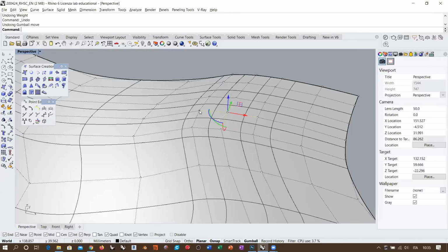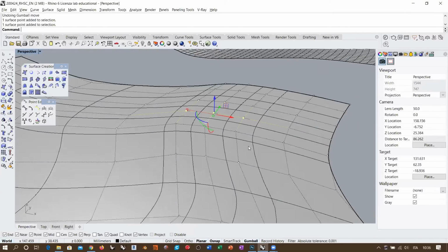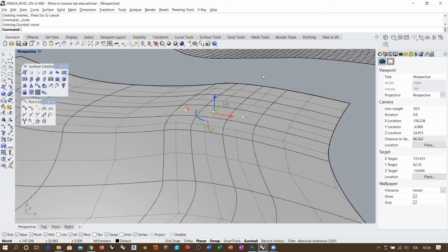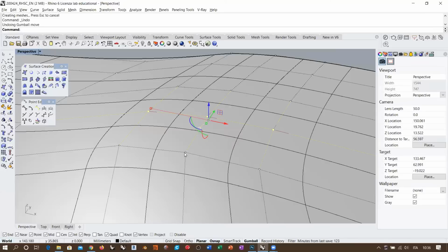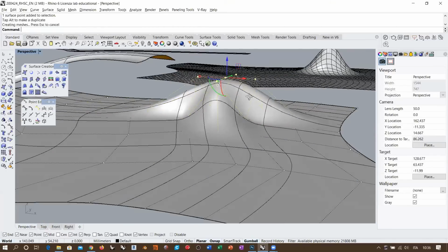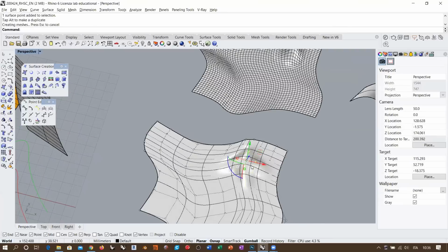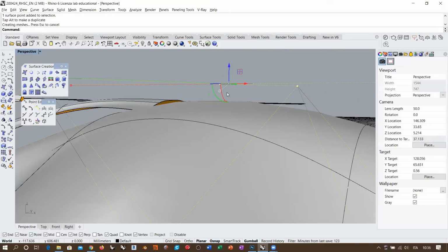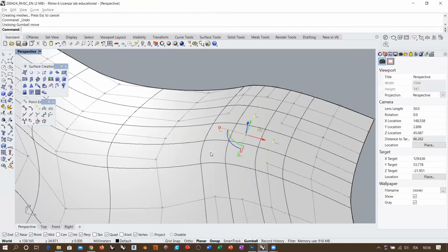So for example, if I take these two here and I move them all up, you see that I create this kind of situation here where the surface is still pulled up but doesn't reach this height. Why? Because the surface is a bidimensional domain. It not only works in one direction, it works in 2 directions at the same time. So in order to get to that height, I also need to consider this and this. And not only this and this, because I am not considering exactly the whole set of points. As you can see, you get this kind of nice cross here, but the surface doesn't reach exactly that height because I still miss these corner points.